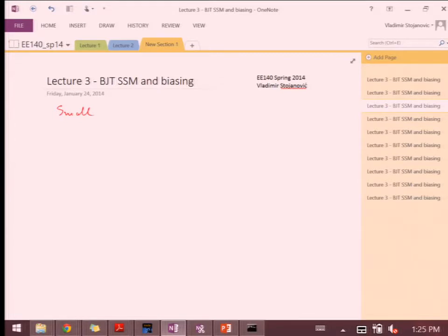There are, though, symmetric PNP and NPN transistors in which the dopings are balanced, in which case the reverse beta will be kind of the same. But mostly people use the asymmetric so that you can handle larger VCE voltages without a huge collector current modulation through the early voltage.